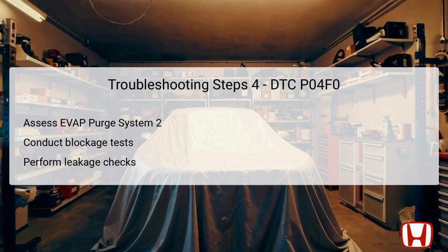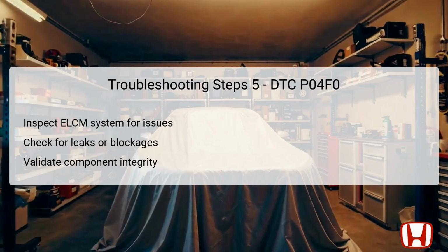These assessments help identify faults within the purge systems effectively and form a basis for remedial actions. The fifth step consists of examining the Environmental Leak Check Module (ELCM) system. This system is integral in confirming that there are no vacuum leaks in the EVAP system.